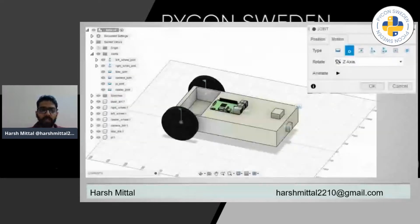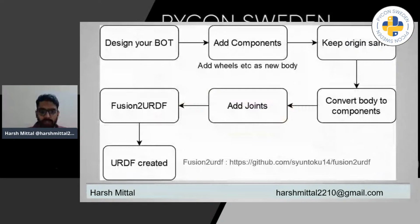Once you are happy, you need to basically convert all the different bodies into components. So over here, you can see on the left hand side, all the different parts are now converted as separate components, right? Once that is done, then you can add joints, like whether it should be fixed or continuous. Then finally, we'll be using open source library, that is Fusion to URDF. This particular library is also written in Python to basically convert your design into URDF files. Along with URDF, it will also create launch files and the world file as well that we have discussed in previous slides.